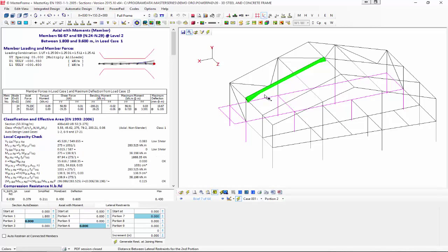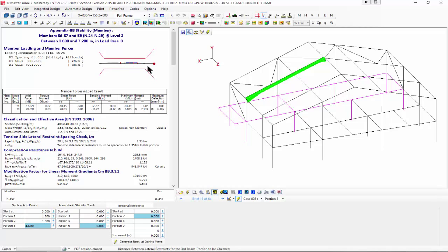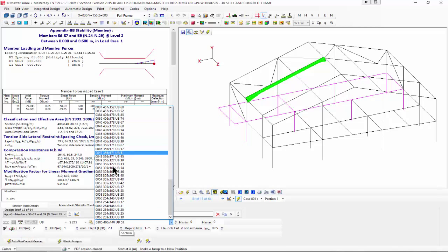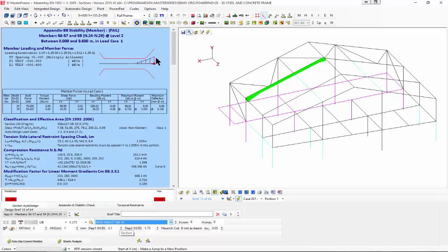And if I come down to this portion, you'll see that it needs the stays, and we can take the stays out and see it happens. Take all the knee braces, and we can see actually for this, it is quite happy to work without any restraint. It's obviously far too big a section for the design. Design wise, I'm just going through. It's very simple. We can either change a section down and see what happens, and we can say, whoa, that's giving us a failure. Very simple, very clear. Blue screens, red little highlights, something's wrong.